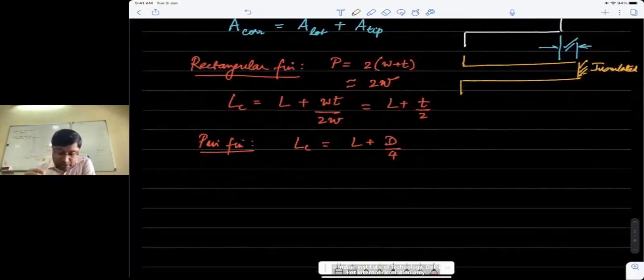So now let me talk about something which is more fundamental than just maths. So far we only looked at maths and how we get temperature distribution or heat transfer rate from a fin. The more fundamental aspect is that there is no guarantee that putting a fin on a device or on a heat exchanger will actually give you better performance. So there is this issue of economy: how much cost you incur versus how much you gain in terms of heat transfer rates.